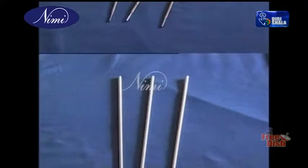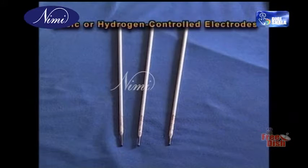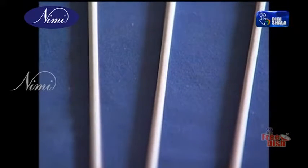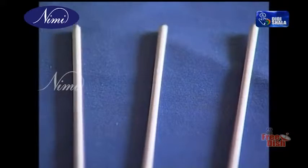Basic or hydrogen-controlled electrode coatings are based on calcium fluoride or calcium carbonate. This type of electrode is suitable for welding high-strength steels without weld cracks, and the coatings have to be dried.